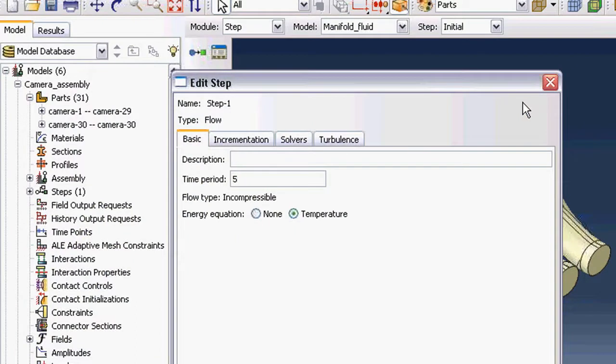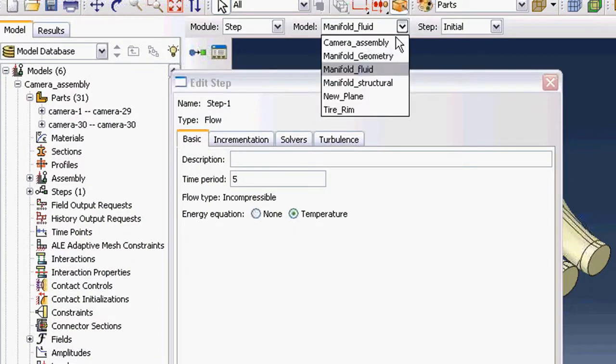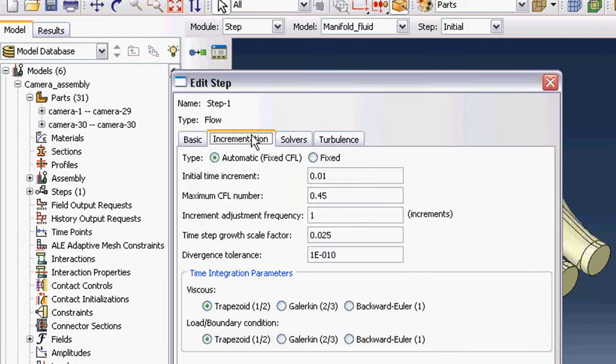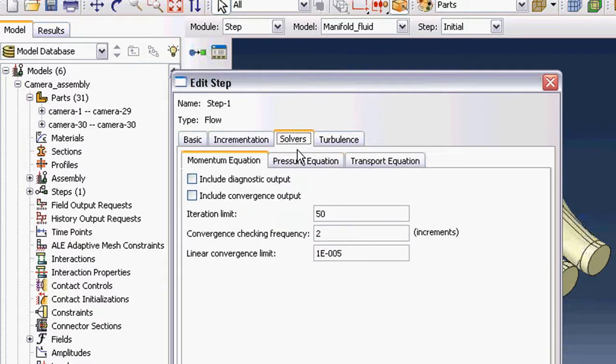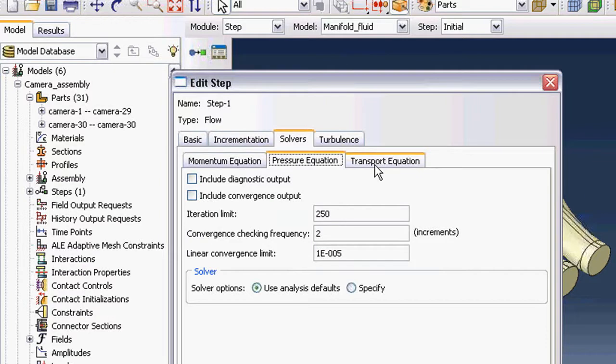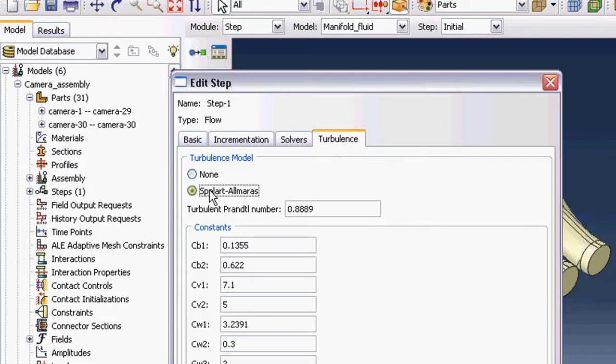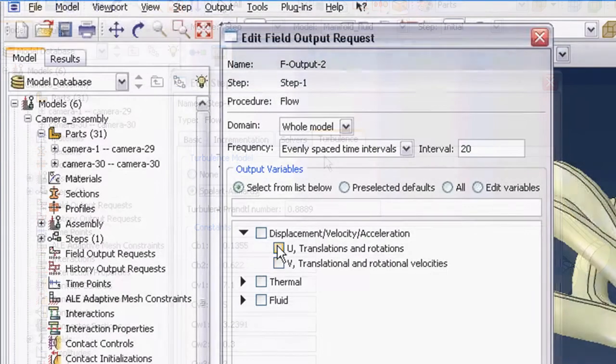So we are almost ready for analysis. Let's go ahead and define the boundary conditions, that is, to set up our scenario. So we'll select or define the load, the method of analysis, the type of analysis, pick the type of solver and equations to deploy, specify turbulence models if you want any, define fluid density, define entry points of the fluids, then exit points, and tell the software what the fluid temperature is, then set up your job. All that is left now is to run the scenario.